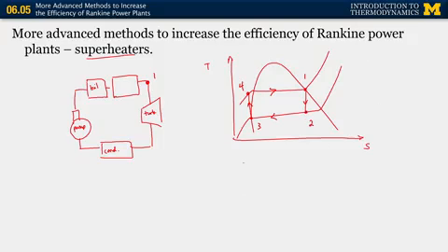Now remember what we talked about last time. For my Rankine cycle, I said we could approximate the cycle efficiency as being 1 minus the temperature at which we reject heat, divided by the average temperature that we add heat. So I want to operate out here in the superheat region because it's better for the durability of my turbine. And if we look at this number here, T in average is defined by these limits here for the basic Rankine power plant.